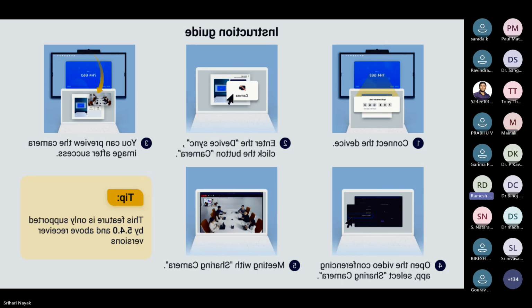Why do you use that block? What's the use of that block? We are using the rate transition block for the initial conditions. It is a data transfer handler between the different rates and tasks.